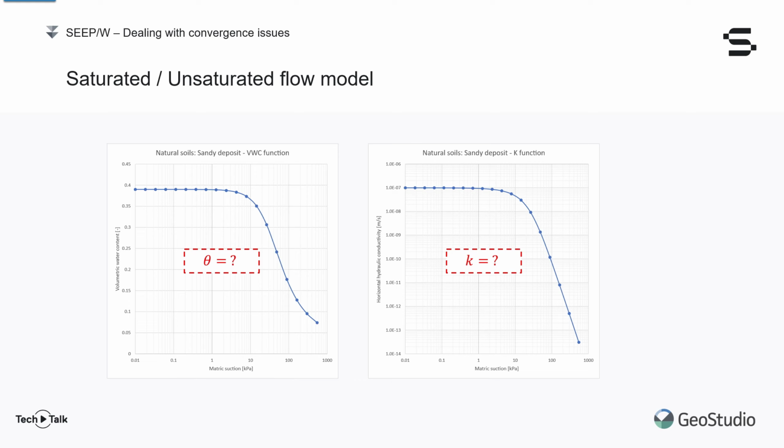Clearly, hypotheses will need to be made to get us going. Note that in steady-state seepage analyses, the volumetric water content function is not used by the solver because water content cannot vary, as opposed to a transient analysis.